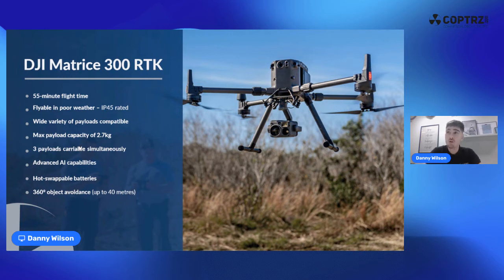So unlike the other drones where you have to turn them off to switch batteries, you can still leave this drone on. If you take 2 batteries, which the drone will come with, you can take one out while leaving the other one in, swap the battery while still leaving the drone on, without having to reset it, without having to calibrate the drone as well. So a really easy and efficient drone with a variety of payloads compatible with different industries, which I'll actually go